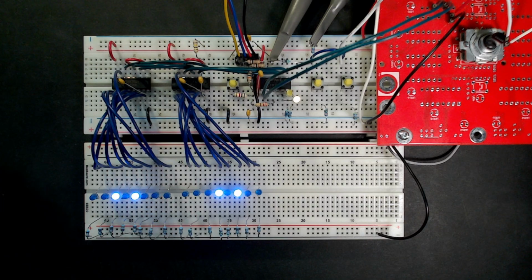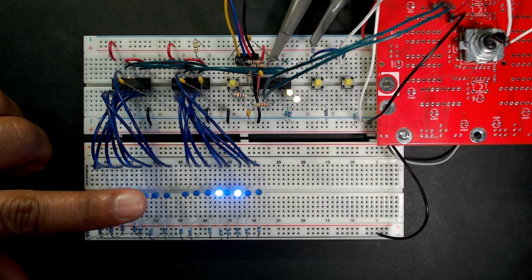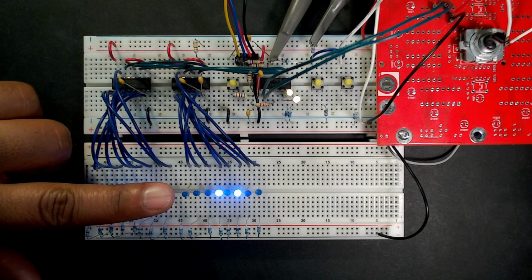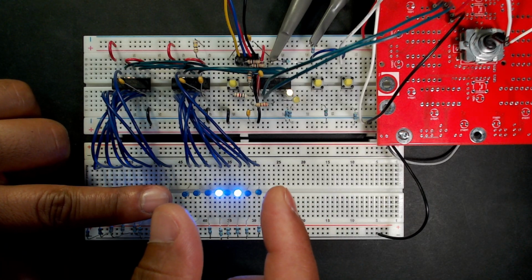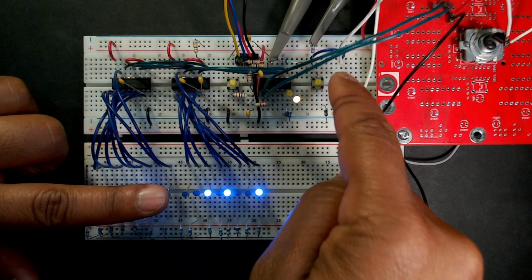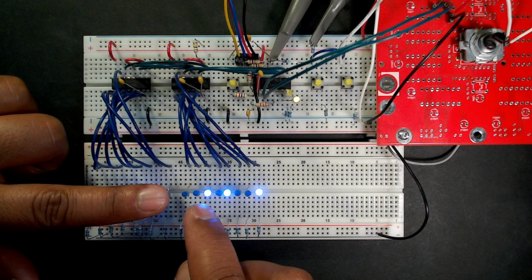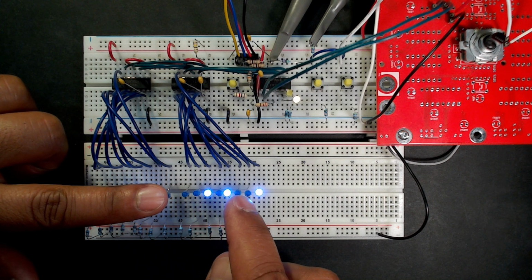Now, the first thing we've got to remember is because we're doing this temporarily, we didn't really do it properly. We have a 16-bit display, but we're only sending an 8-bit output. So really, we should only be paying attention to the first 8 bits of our display and ignoring the higher 8 bits. Which means these 8 bits over here, we just need to ignore them and only look at the lower bits here. So if I push this button, the result that shows up looks to be, well, that's a 29. So this is hexadecimal 29.